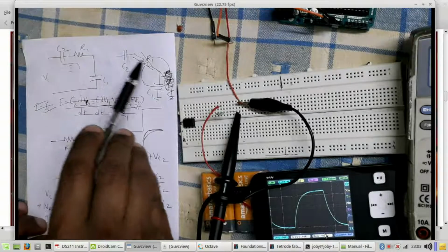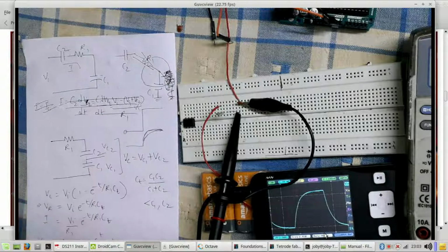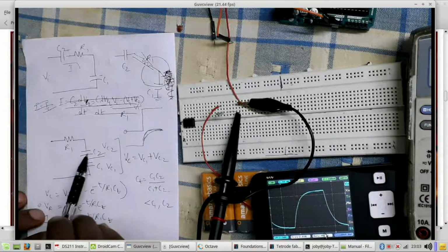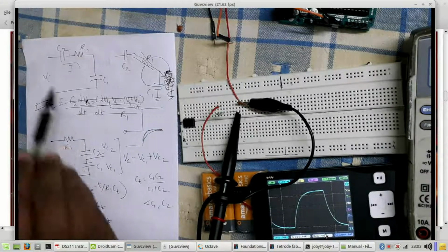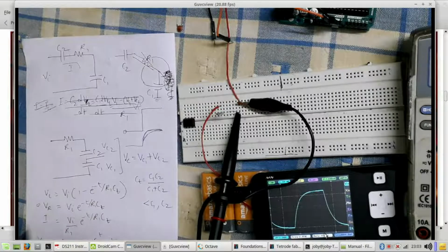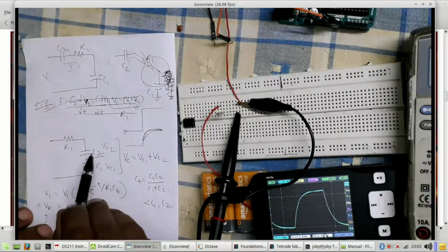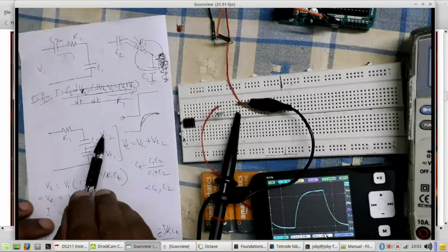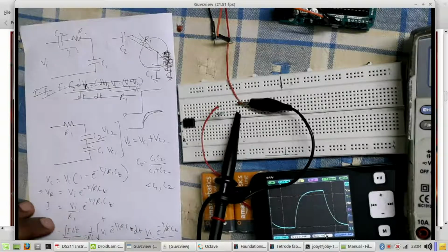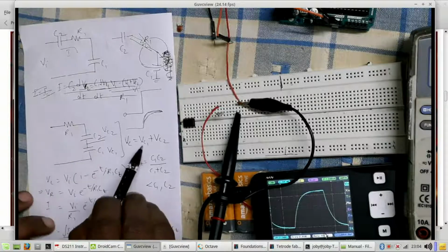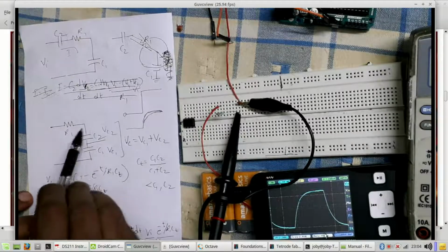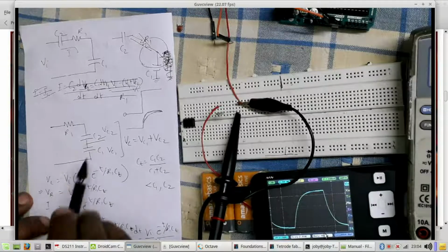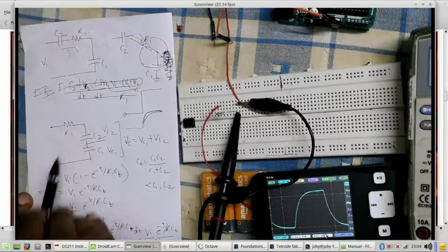Now how would this circuit function, right? To look at that, maybe we can abstract it, the C to be here, because it's in series. It doesn't matter where you place this capacitance. So the net capacitance here is this in series with this. Each of them has the corresponding voltage across them, VC1 and VC2. Okay, and so the total VC is the sum of these voltages. So if there is a net capacitance here, which we know will be this because they are in series, then this circuit acts as a single RC circuit.